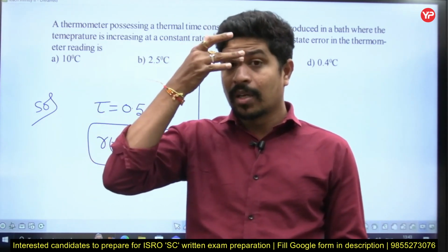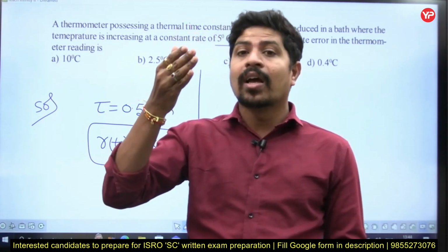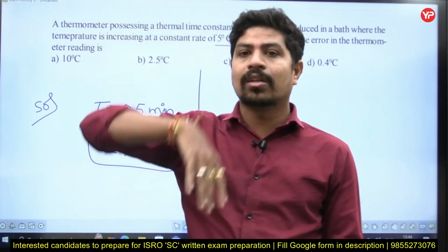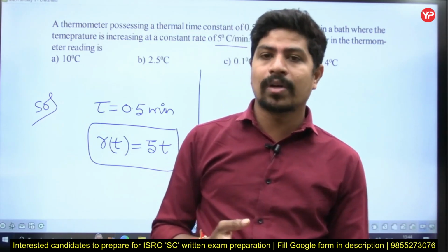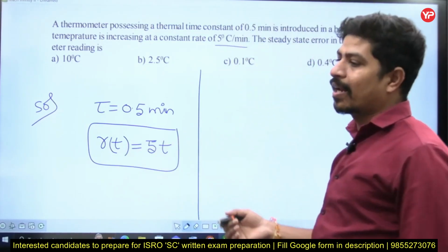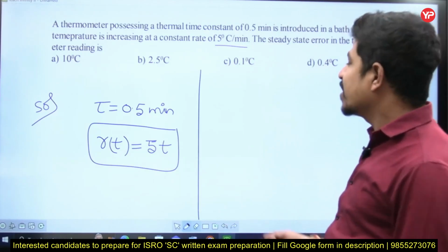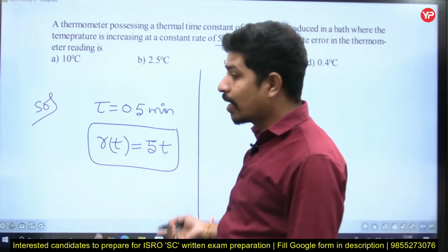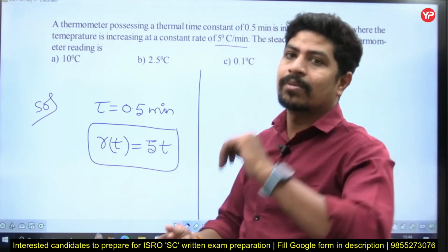Constant magnitude throughout the time. The input which is having constant acceleration is called a parabolic input, right? These are our standard inputs. Now, the question is asking about steady state error. He is saying that he has given a ramp input for a type 1 system.